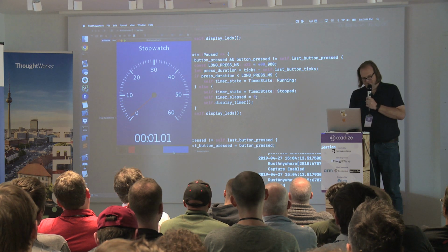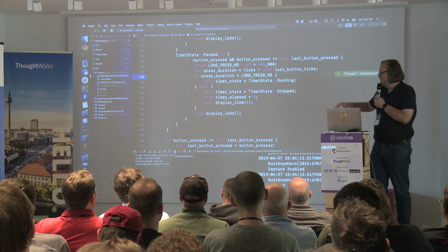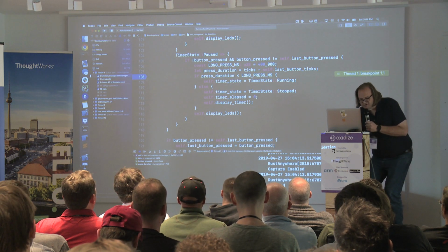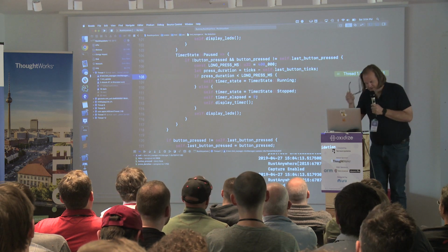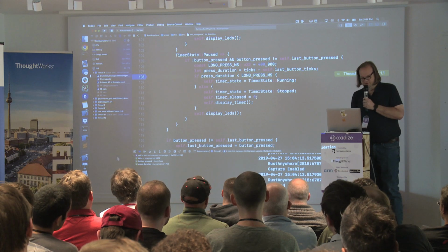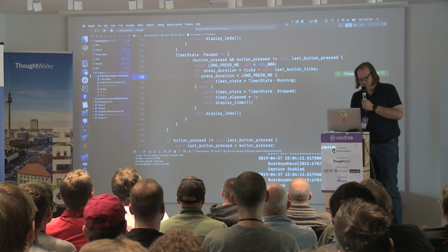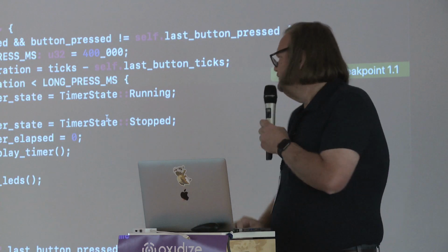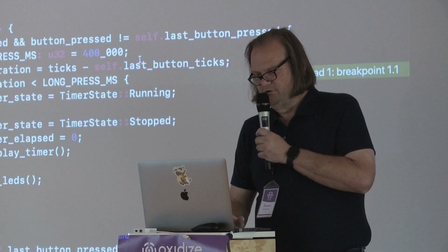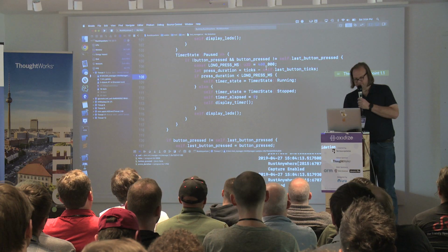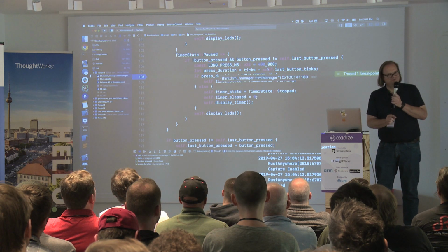Let's start it. The long press, release, boom. Okay, it's hit the breakpoint. It's actually brought us to the line of code. We can look down here and see that it was about half a second that I waited to press this. Unfortunately, it didn't trigger what we wanted. It's only a couple hundred milliseconds, but wait a second here. We're looking to see if the value is less than 400,000. Looks like somebody confused microseconds with milliseconds.